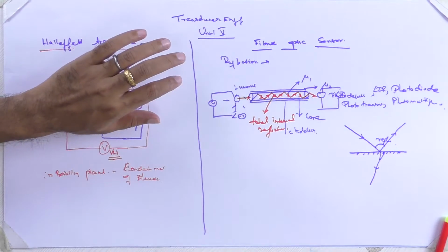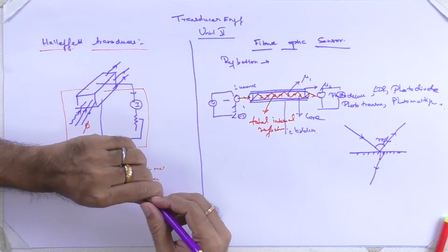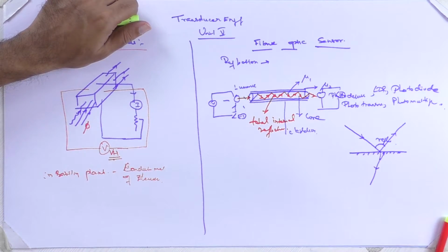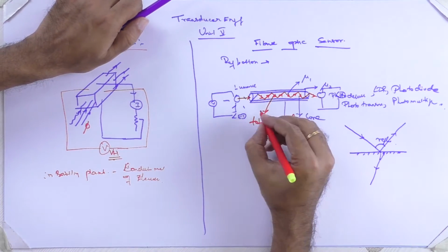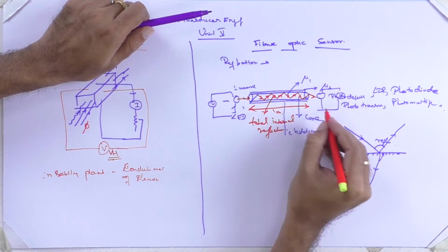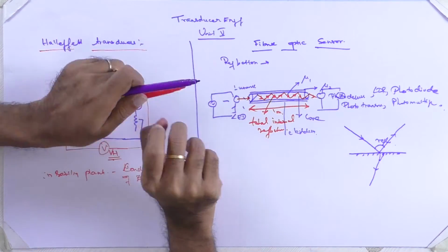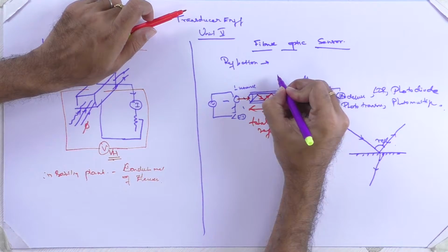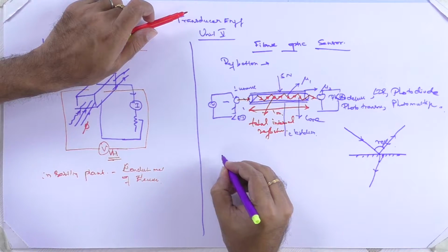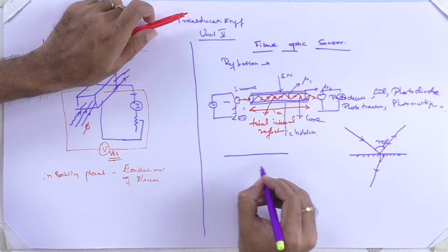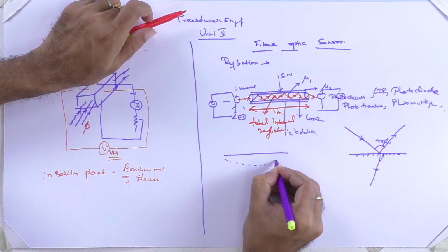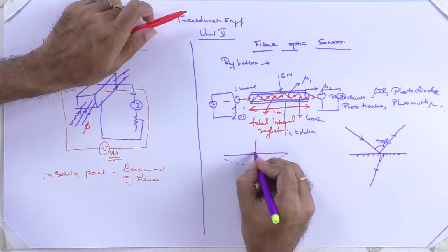Okay, now how are we going to convert this fiber optic cable into a sensor? Just I will tell you an example for force. Now let us imagine this is 1 meter long, okay, and we are getting the entire signal outside. We are applying a force of 5 newtons to this fiber optic cable. What will happen immediately? This is the cable without any problem, and then there will be a curvature happening over here because of the force applied.